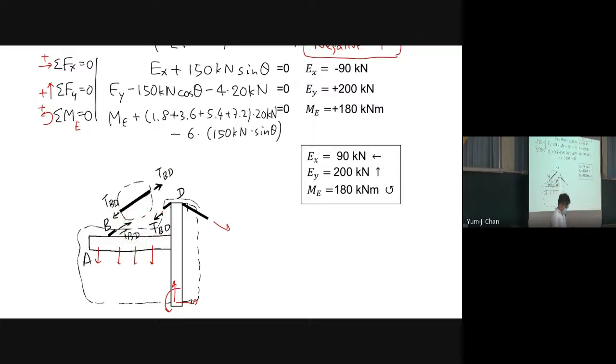And you can work it out from physics or mathematics. If we do it from statics, because this is a rigid body, this force can be moved along the line of action to here to cancel out this force. Okay, that's the first way of explaining this.